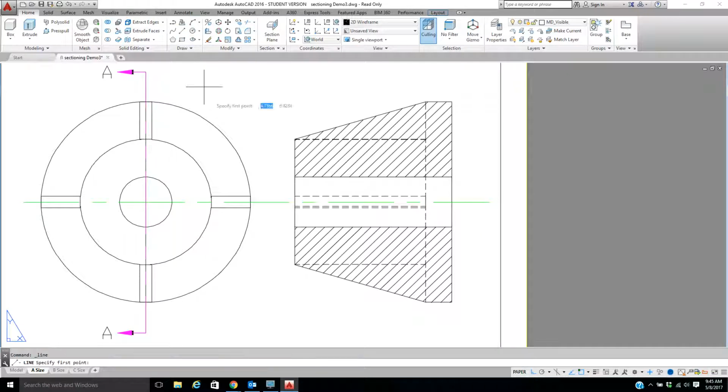So I'm going to go in here with some lines, and I'm just going to pretty much draw over these hidden lines here. And I'm going to make the full area around it so I can hatch that. Like that. So I drew over top. I'm going to do it again to this side. Now this is quite backwards. By rights, it should hatch properly, but like I said, AutoCAD hasn't figured out this part yet with it. So now I've done that. I've just traced over these lines.